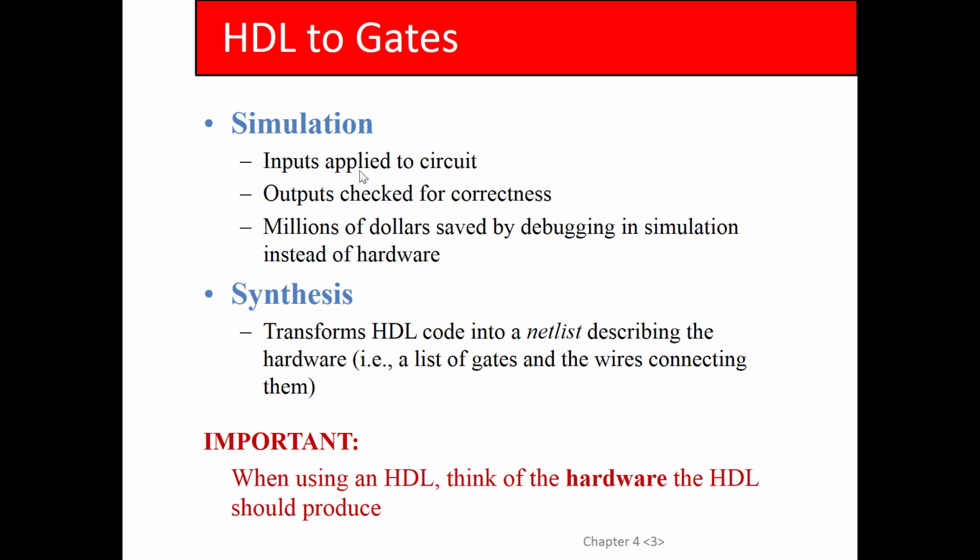So when you have a traditional high-level language like Java, it's compiled to some executable form. It's kind of the same idea with HDL, except it's compiled down to a schematic of gates and wires that could be either implemented on a programmable logic device like an FPGA, or you could use it to design a chip that you're going to send to a fab and actually have made into an application-specific integrated circuit, an ASIC.